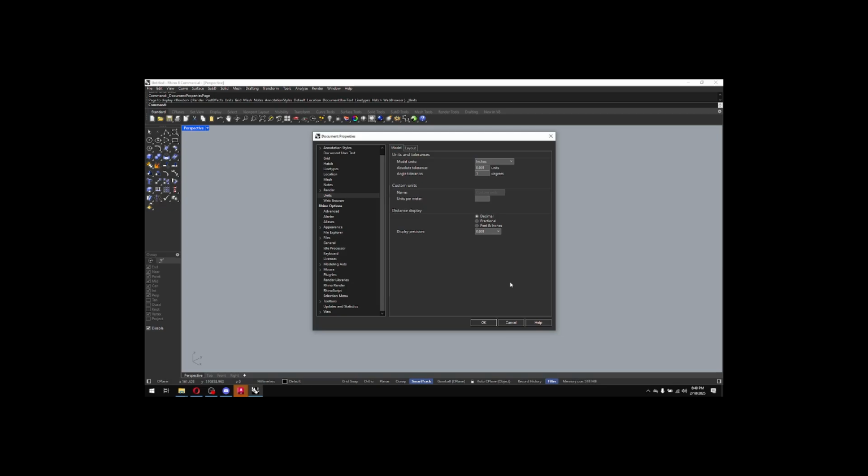I like to default to inches, so I can just type 8 and it knows I mean 8 inches, but I could type 200 mm, it understands I mean 200 millimeters without changing this. So you can add the little signifiers to the end of any number and it'll understand what you're working towards. But again, usually working in inches.